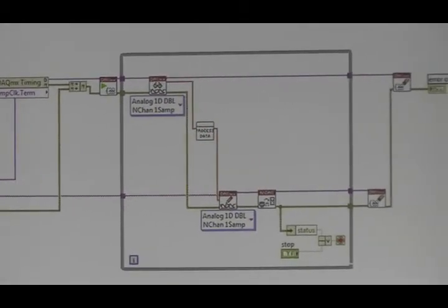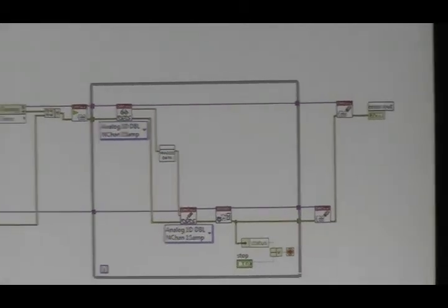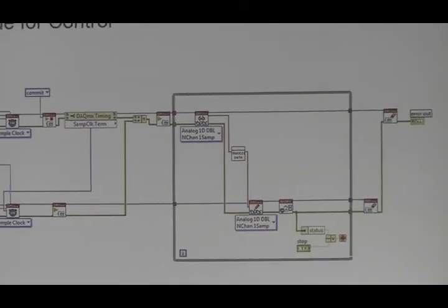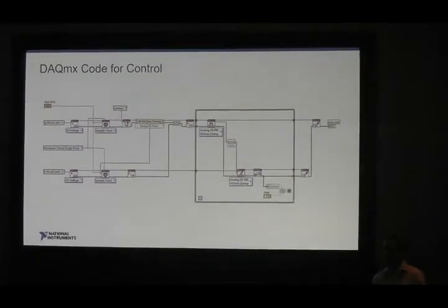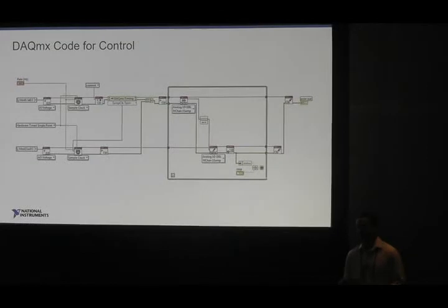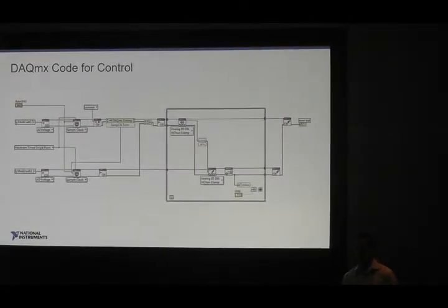You will now have some configuration you have to manage outside of the control loop compared to just dropping a node in. But the nice benefit is you can now potentially achieve rates up to 5 times that of what you were doing previously with RSI. And so now you have more capabilities to expand beyond the loop rates, which is something we've heard from this group before: I want to use RSI, but I need to go somewhere between 1 and 2 kilohertz. And this does that pretty well, where RSI may have struggled a little bit to potentially meet that in the past.